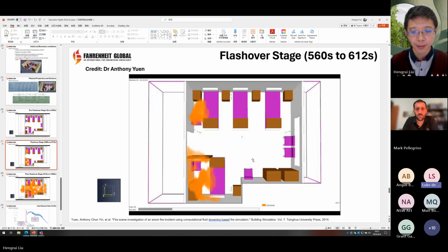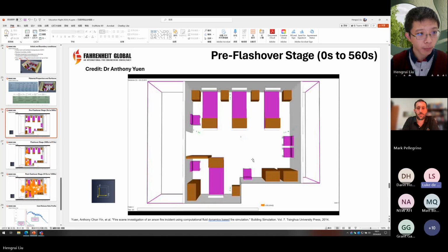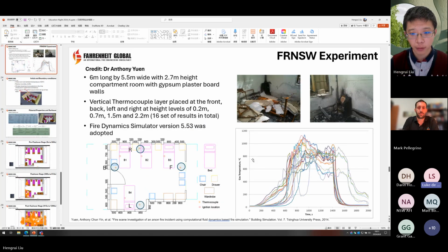Thank you for the presentation, very interesting. I just had one question about your forensic modeling of the Quaker Hills building. Apologies if I've missed it, but it appears you did some experimental burn and also some FDS modeling, with some pyrolysis modeling in there, which is very nice to see. The window breakage was obviously a significant event in your FDS model. Did the experimental burn have a window in it as well? And did that pop out at the same time?